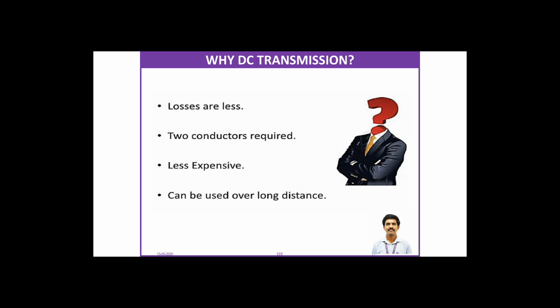Why do we want to go for DC transmission? As I said, only two conductors are required, it is less expensive, and it can be used for long distances, so the losses are very much less compared to HVAC.